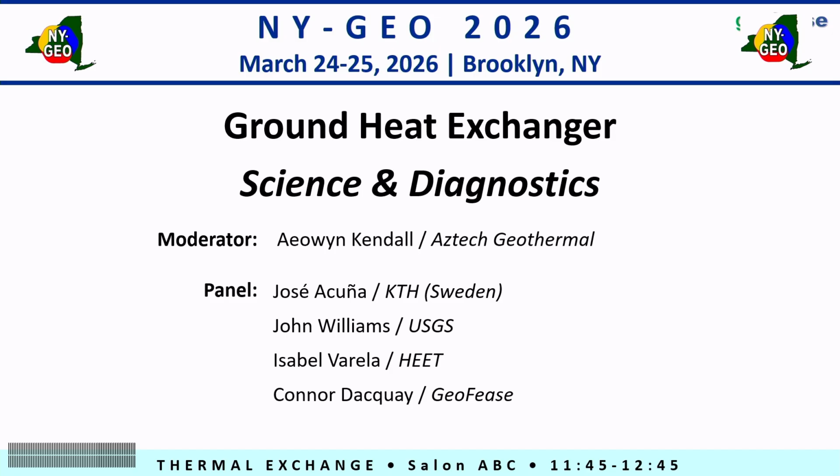Yeah, so the well we just logged, that Lyons one, we also did a 400-footer that they just drilled, and I don't know, Kevin, if you even saw it, but it was like 1 degree off. So that's in part the geologic environment, but it also reflects the driller as well. So. That actually happens the bottom 30 feet. Sorry, yeah, that last little bit was a formation change. We went from shales into a really hard limestone, and that kind of kicked it just a little bit.